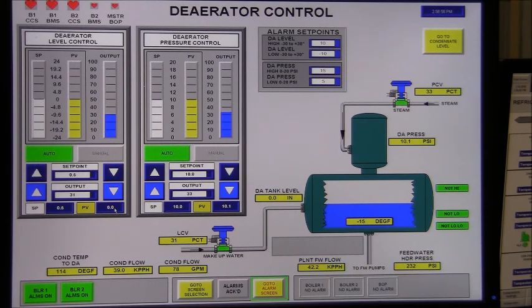The PV, process variable, is the actual tank level, and the tank level is scaled from -24 to +24 inches. You can see that next to the vertical bar graphs, how we've scaled it. We do that so that typically 0, or the middle of the tank, will be the 0 operating level. This is scaled in inches, as the transmitter is calibrated in inches of water, -2 feet to +2 feet. The operator enters the desired level in inches of water. The operator entered set point is displayed down here.